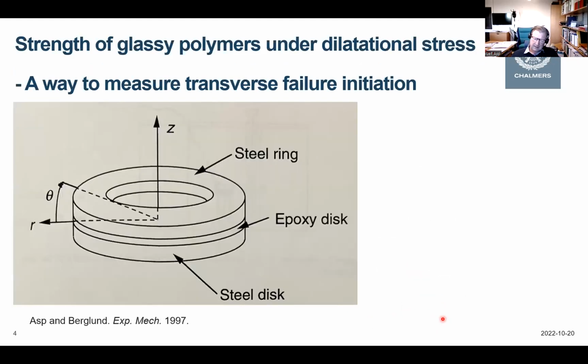As I'm sure Ramesh will talk about, it's of course an event of failure initiation, and also a failure progression that follows. For thin plies, we expect that failure initiation will happen, but we don't see cracks growing. For thick ply composites, we get more or less immediately a transverse crack forming after failure initiation, and we get these very low strains to failure.